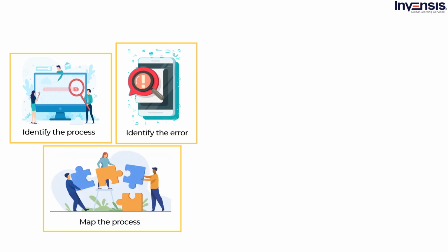Map the process by identifying the risk. To do this, it is better to be in a team and then start the implementation process. So, sit with your team, review each step in the process flow chart. If you do not have a process flow chart, create one. Then, check for any areas where defects have occurred in the past or have a high potential to occur. Next, brainstorm all the possible errors that could occur within the process. Then, try to resolve them.